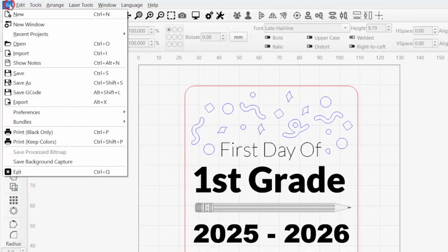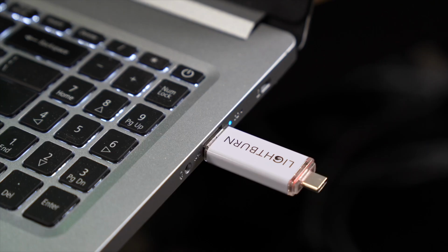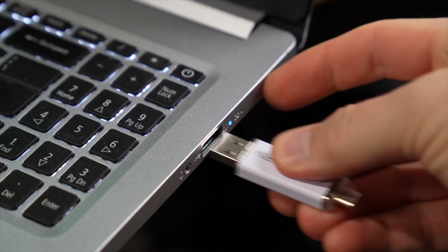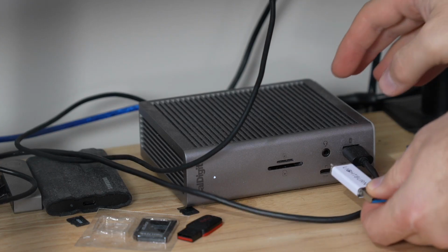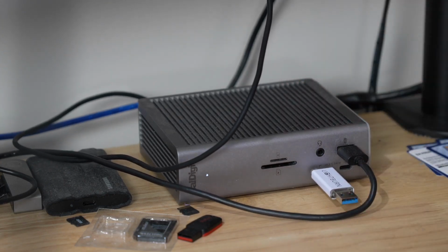If you want to move designs containing text between computers and continue to edit the text objects, be sure to install all necessary fonts on the computer you'll be using. When saving a copy of a file containing text, LightBurn automatically includes a copy of the text as a path and embeds it into the file.